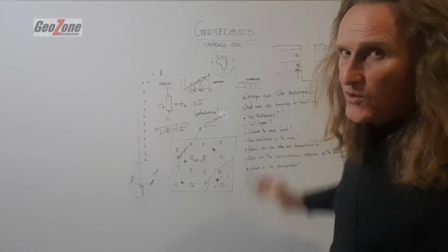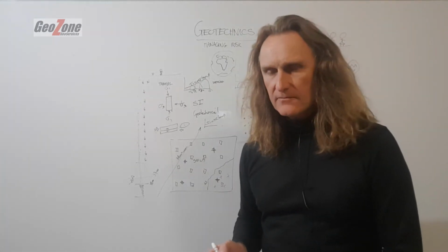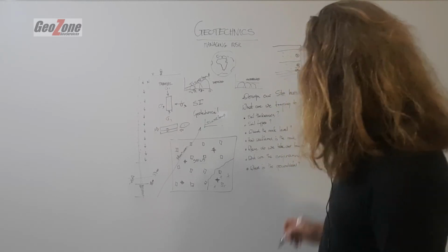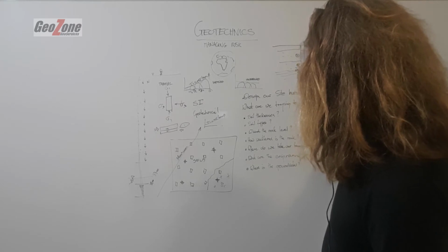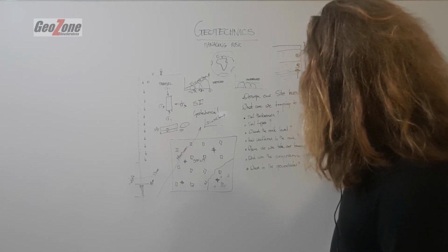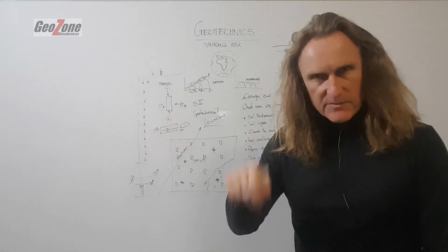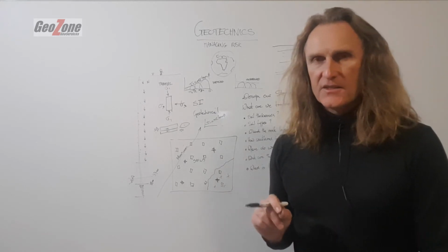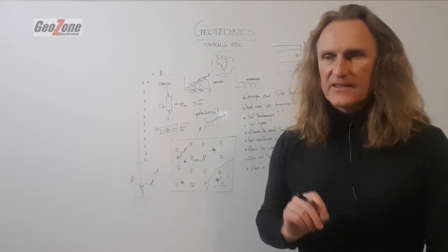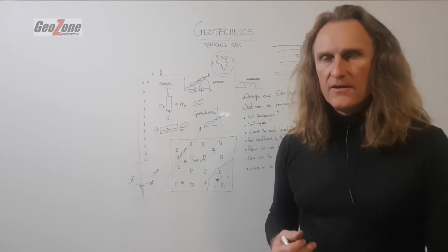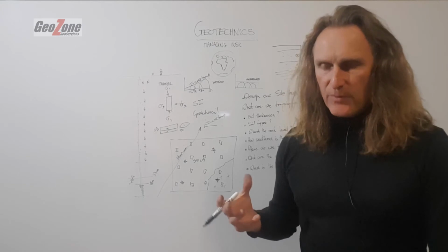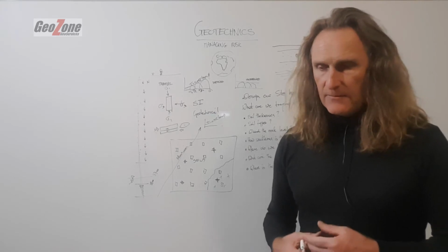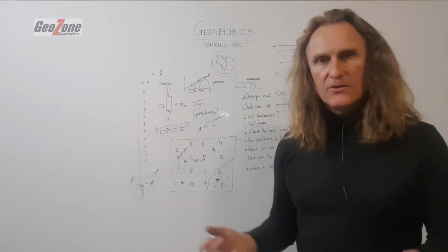We can understand. The water is very important. No one pays attention to this. We could actually just stick a piezo in here. It's not the best way of doing it. And backfill the hole. At least at some stage you can come and put a dip meter down and we can measure where the water is. Water is incredibly important in terms of foundation design. And it affects your shear strength, it affects the in situ weight of the soil. There's a buoyant effect of the water trying to lift up the in situ materials. It affects your consolidation, it affects your heave. So we need to pay attention to these things.